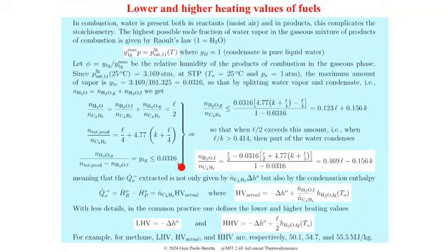If you combine all that, you get that the maximum amount of water that can stay in the gaseous phase is limited by this combination of the L and Ks that describe how many carbons and hydrogens you have in the fuel molecule. And when you have condensation, which happens when L over K is greater than 0.4, this is the amount that condenses.